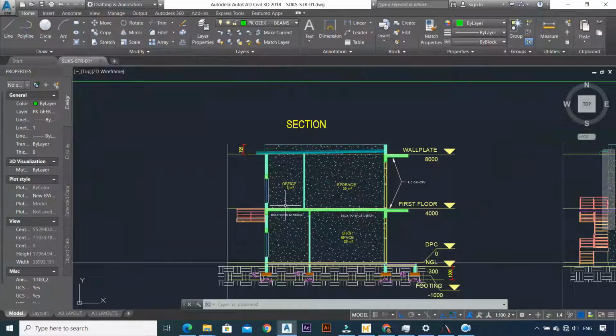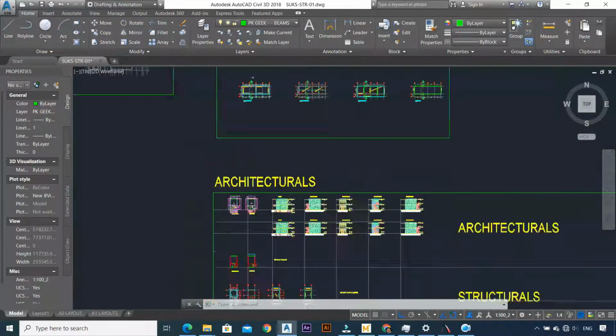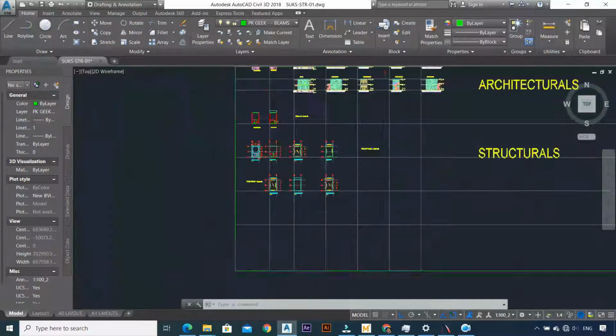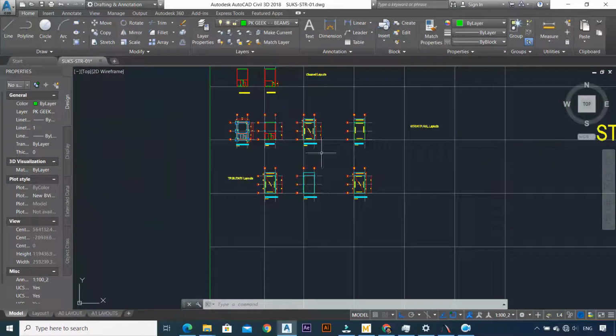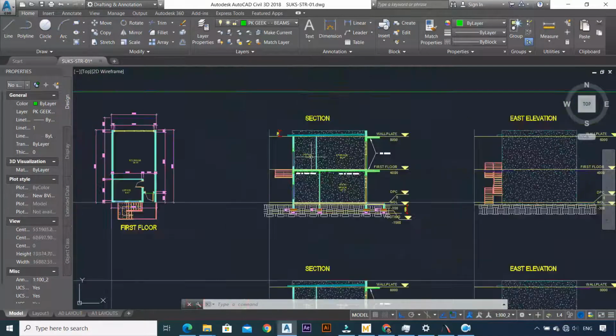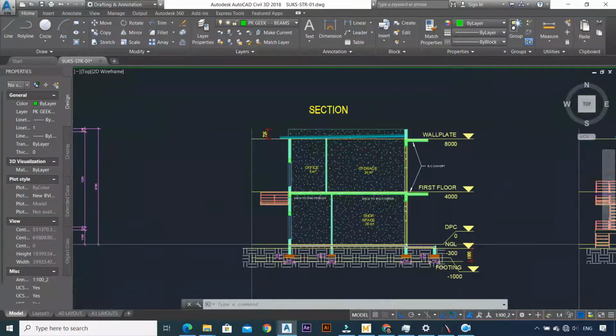So essentially, that is where your loads are going to be coming from. So walls onto beams and beams onto columns. Same here. It's actually roof and walls onto eaves beams, and then those beams onto columns. At the first floor, it's essentially walls and slab onto beams, and then those beams onto columns, and then everything from the columns down to the foundation. So that is cool. So as I'm saying, that is why we are going to be using it, because it's essentially the same thing.